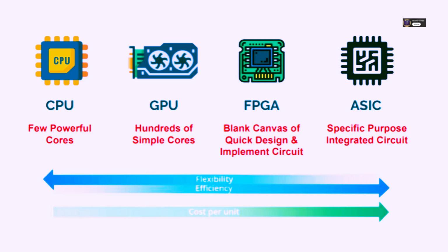Now for the real deep dive, the trade-offs. Let's start with something the interviews kept bringing up, the latency war. If a GPU is this parallel powerhouse, why would an engineer ever choose an FPGA for speed instead? This is such a critical distinction. It's about the nature of the speed. See, the GPU offers fantastic throughput. It can process enormous amounts of data very quickly, in total, aggregate speed.